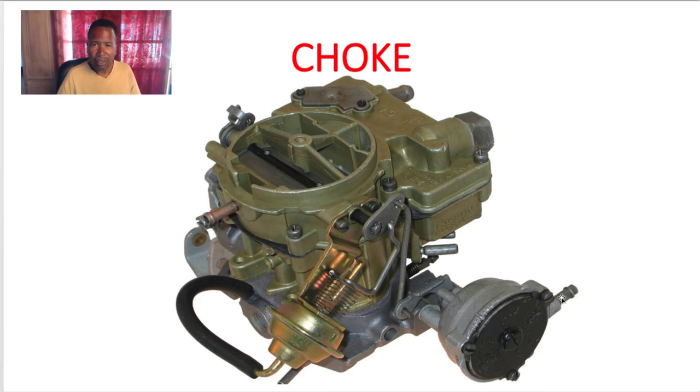The heat that comes when the car starts up heats it up and it starts to relax. Eventually, when the car is totally warmed up, this choke has to be all the way open. It cannot be closed in a warm car because it runs too rich. As a matter of fact, it runs so rich that if I make a vacuum leak, it'll smooth out because I'm adding more air to it. So in a warmed up car, that choke has to be open. On a cold car, this choke has to be closed when you initially start. And once it starts, the choke pull-off cracks it a little bit, about 1/4 of an inch, to let a little air in and mostly fuel go through the circuits. If this choke was not set up correctly, you have a hard start cold or start and die cold situation on your hands.